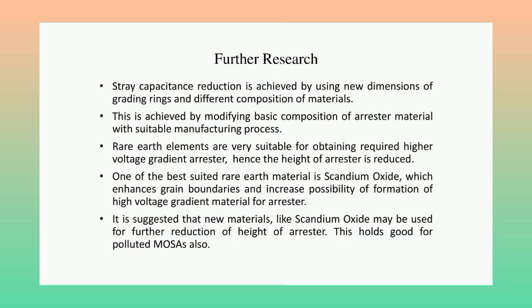Further research. Stray capacitance reduction is achieved by using new dimensions of grading rings and different compositions of materials. This is achieved by modifying the basic composition of the arrestor material with a suitable manufacturing process. Rare earth elements are very suitable for obtaining a required higher voltage gradient arrestor, hence the height of the arrestor is reduced. One of the best suited rare earth materials is scandium oxide, which enhances grain boundaries and increases the possibility of formation of high voltage gradient material for the arrestor. It is suggested that new materials like scandium oxide may be used for further reduction of the height of the arrestor. This holds good for polluted MOSAs also.